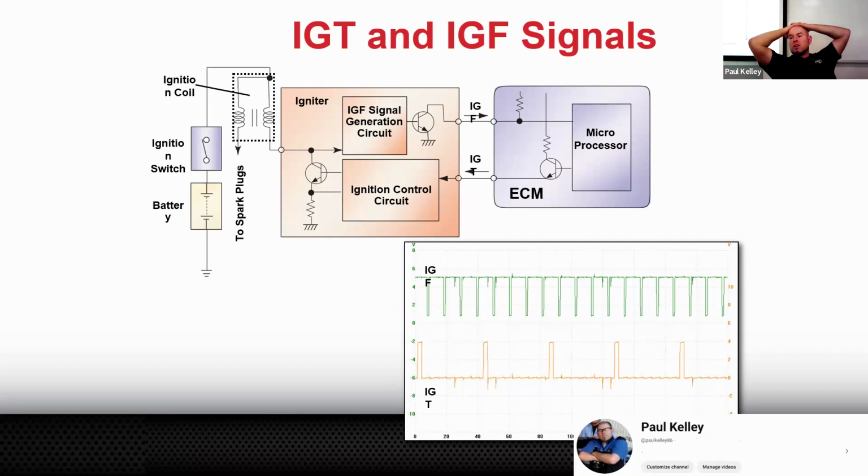True, but first it goes through something in the exhaust. And the catalytic converter will get nuked like in a couple weeks or less. So the manufacturer's like, hey, if we don't have spark, we want to set a code quickly so that the customer brings it in right away so they don't fry the catalytic converter and have worse emissions, right?